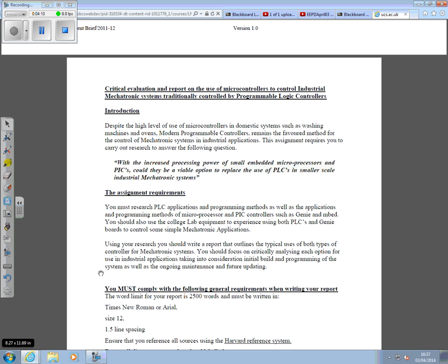What you need to look at here is that the PLC programming language is designed to be, in essence, understandable by someone who's used to traditional electrical diagrams. The ladder diagram format, whether or not you like it, fits that. Someone who's spent years working with traditional relay electrical circuits would have a good chance of understanding PLC logic.